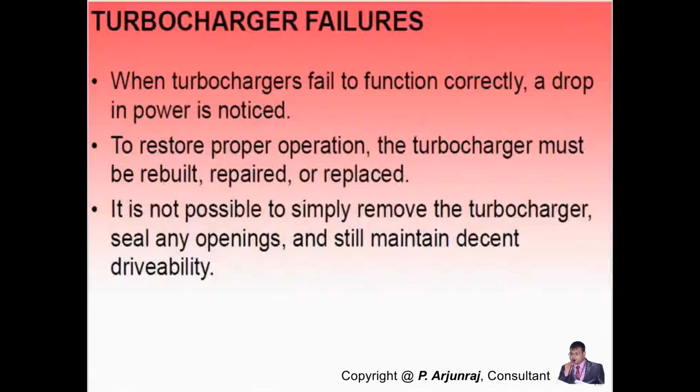So based on that, when you find the boost pressure higher, you get the response that the valve should be in closed condition. Accordingly, it is electronically controlled, and that valve or the throttle gets closed when you get the sensing that the boost pressure is on the higher side. In olden days I started with a manually adjusted one, but now it's completely electronically operated. The adjustment is happening electronically.